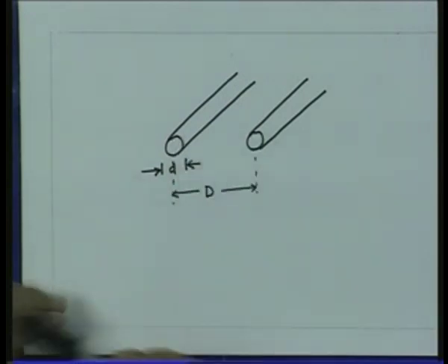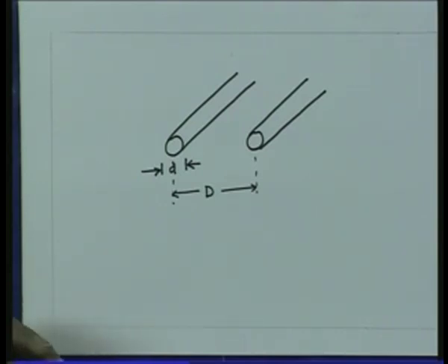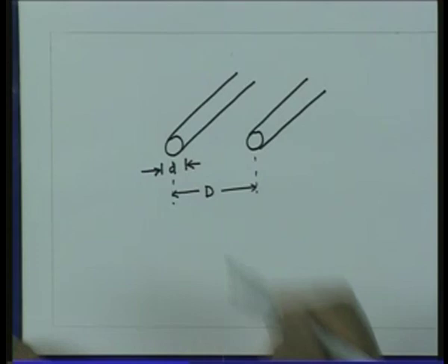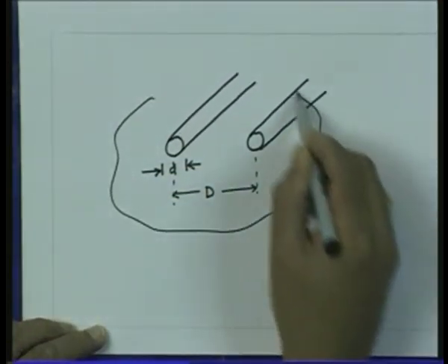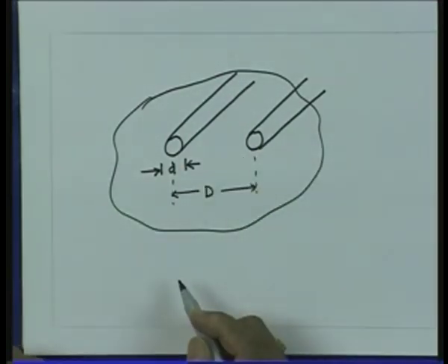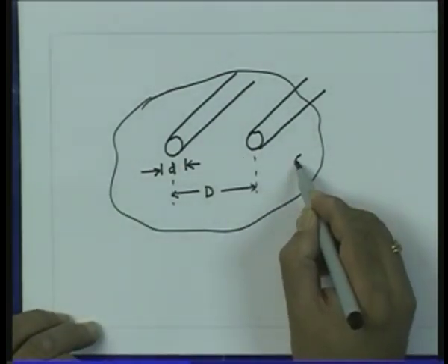You can also see this structure whenever you use the flat ribbon cable for connecting a Yagi antenna to TV. The flat ribbon cable which runs from the Yagi antenna to TV is essentially a parallel wire structure, and in that case there is no air medium, you have a plastic encapsulation on that. So, there may be some kind of encapsulation, and then this will be filled with a dielectric material with some dielectric constant epsilon r.